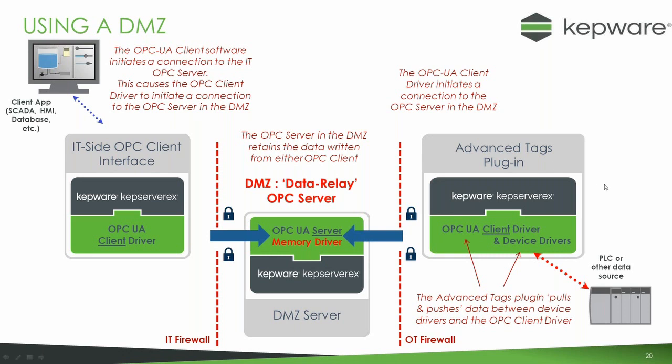Now, some people say to me, well, that's great, but there's quite a few steps here, and if we want to make changes, then you have to manage it in multiple places. Yes, you need to manage it on the copy of KEPSERVER on the OT network, and you need to manage it in the memory driver in the middle. But if your system is very heavily locked down or validated, you don't really want changes to be trivial anyway.